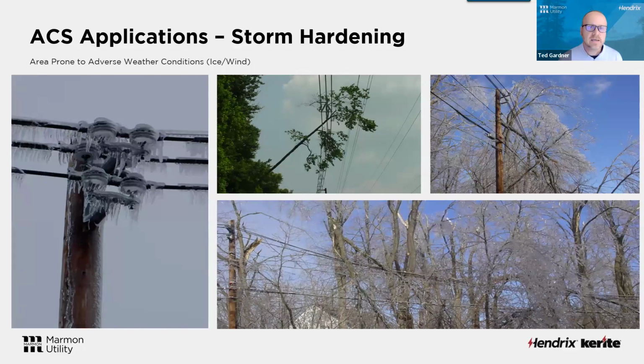So a lot of times they'll start with their worst performing circuits, right? And you can walk into any of your line crew rooms and say, here's our worst performing circuits. Take me to the trouble spots. And a lot of times it's going to be in heavily treed areas that either don't get trimmed very often, or it's just a species that grows really fast, or they've got landowners or homeowners that are running them out of there anytime they come in and try to trim the trees. So those are typically good places to start.